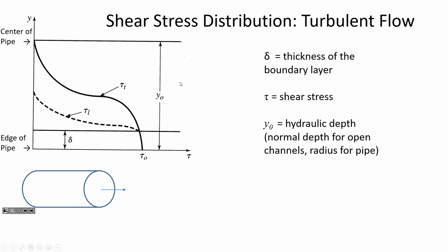We can also think about in terms of how big is the cushion that is laminar. And that's going to be an important one for us. Is like how far from the bottom of the pipe upward is the conditions laminar. Remember, laminar is any Reynolds number that's 2,000 or less. So if the water's moving really fast, then it could suppress the thickness of the laminar sublayer. If the velocity is moving slowly, then the laminar sublayer may be relatively thick. And if the water's moving really slowly, then the entire pipe may have laminar flow.